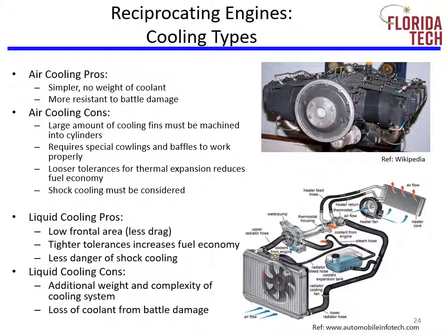Liquid cooling is similar to what cars do. A coolant is pumped through a radiator. Some of the pros and cons of liquid cooling are it's a low frontal area, less drag, and you can get tighter tolerances, which increases fuel economy and less danger of shock cooling. But the cons are there's additional weight and complexity of the cooling system and loss of coolant if you get battle damage.